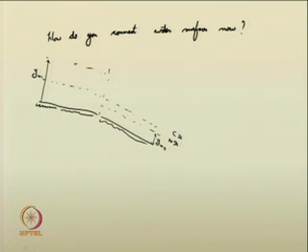So, you may possibly think of a situation where the water surface may join in the following form, that is, it is having the uniform flow up to this junction in channel 1, and then all of a sudden it decreases like this with an M1 profile. Okay, with an M1 profile, sorry, my beg pardon, this is a steep channel. It decreases with an S1 profile. Is this possible? You have to verify it.